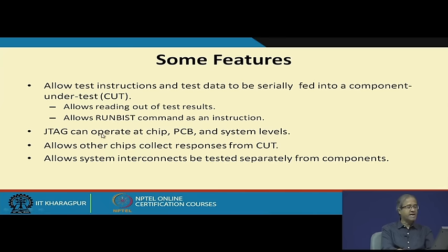And the standard is hierarchical. So, you can work at the chip level, PCB level, and also at the system level where there are multiple such boards connected. The serial output from one board can go into the serial input of the next board. Like that you can chain them. This is a hierarchical kind of standard, not only meant for chips on a board. On a single chip you can do it, multiple chips on a board you can do it, multiple boards also you can do it. Okay.